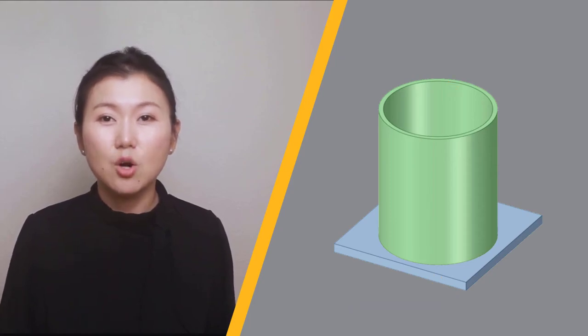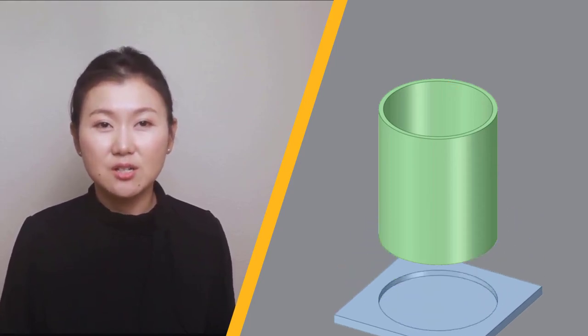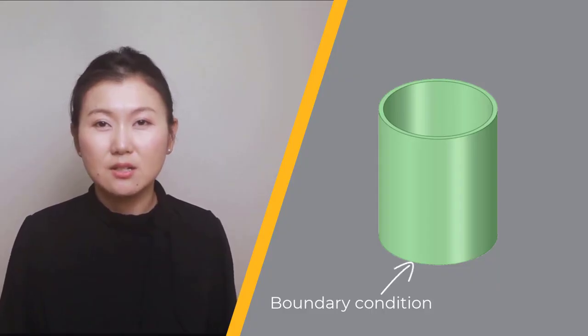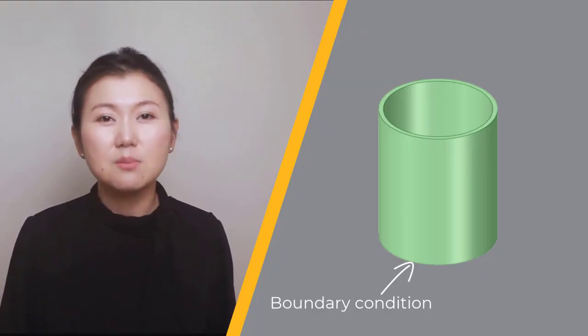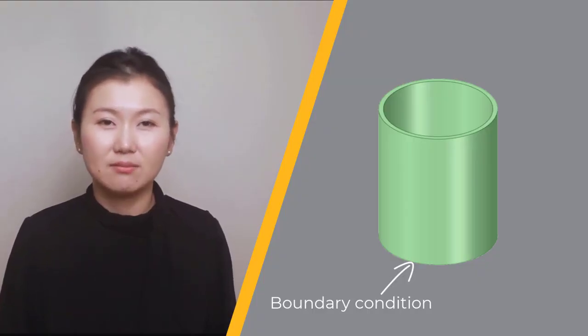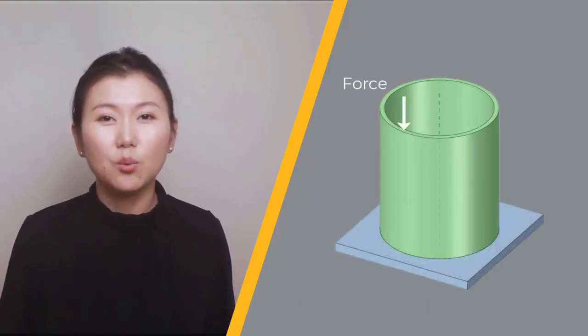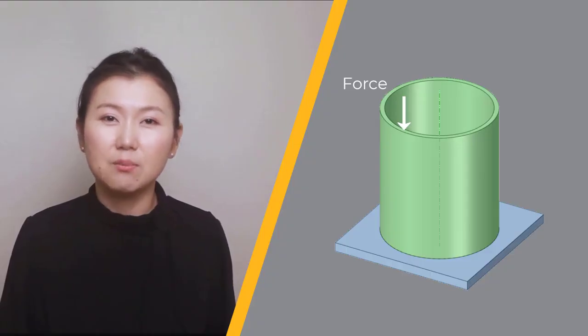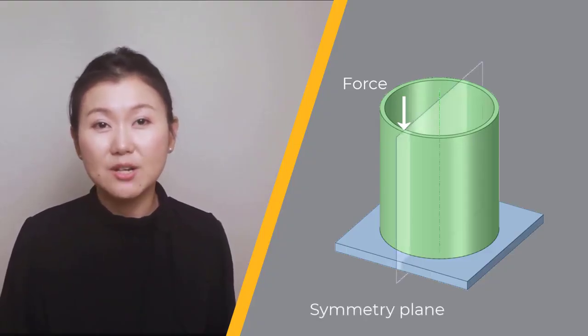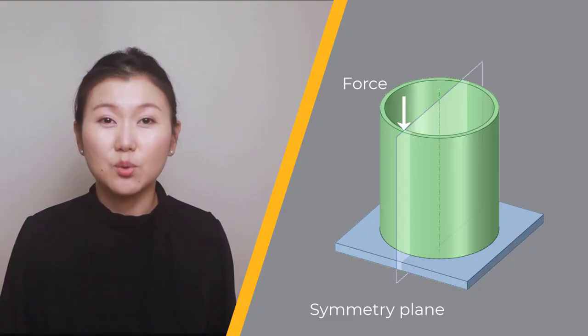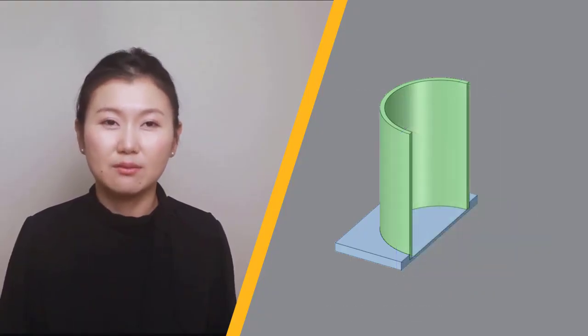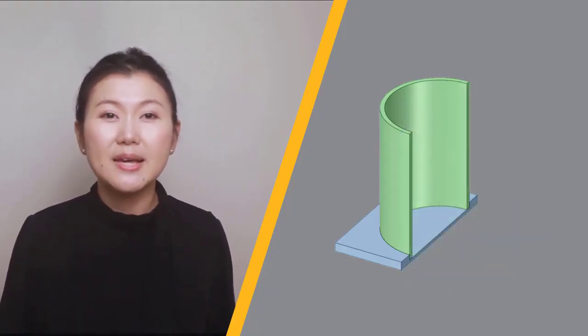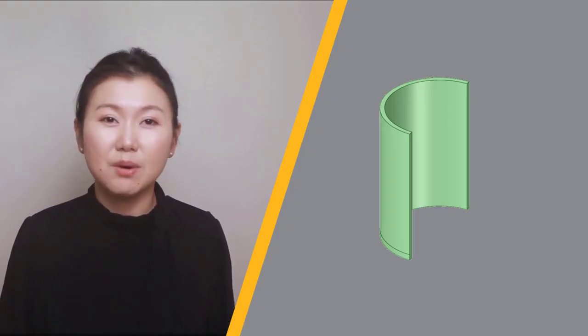Now, in this model, we'll use an appropriate boundary condition to replace the base, so that we don't need to worry about frictionless contact, and doing so simplifies the calculations. First of all, we notice that the behavior of the model is expected to be symmetric about this plane. So we just need to have half of the geometry. And also, the base can be removed as we will use a boundary condition to replace it.